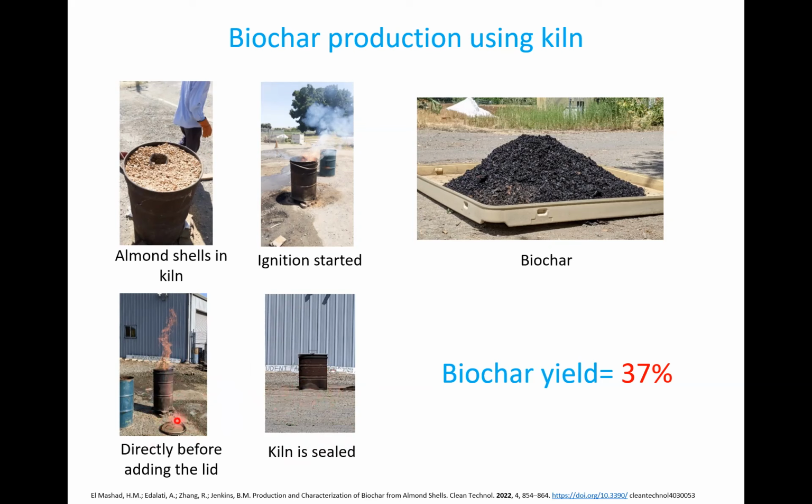on the ground, so there is no flow of air anymore through the system, and then seal the top with the lid for 2 hours or 3 hours, depending on the process that you would like to keep. Normally, maybe 2 hours is enough to produce this kind of biochar here. So again, this is just a very simple system for producing biochar in a small kiln.